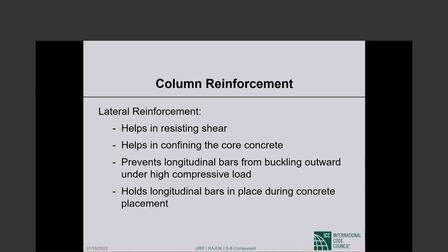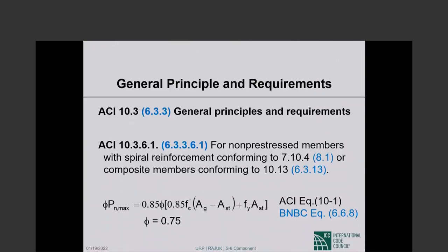Now, even at a more basic level, the lateral reinforcement holds the longitudinal bars in place during concrete placement. And that is definitely not unimportant. Okay, you cannot just have the longitudinal steel and not the horizontal steel if you're going to place concrete. So: resisting shear, confining the core concrete, meaning the concrete inside the lateral reinforcement, preventing buckling of the compression bars, and holding longitudinal bars in place during concreting.